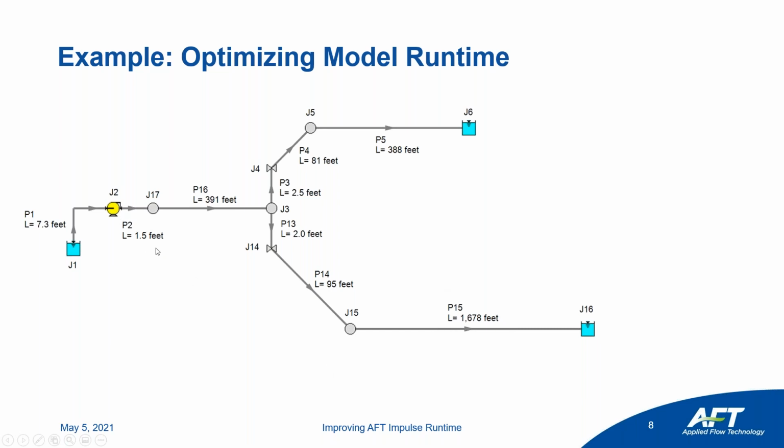So if this one section is 1.5 feet, we already have more than 1,000 sections to calculate in just this pipe. We can also see a potential conflict in different small pipes where we have 1.5 feet here and 2 feet here. That'll cause some issues with variance, where we're trying to make both have similar length sections, but without rounding one or the other too drastically. That could lead to a section length of only 1/2 foot, which will triple the number of sections in pipe 15, again, really compounding the issue.